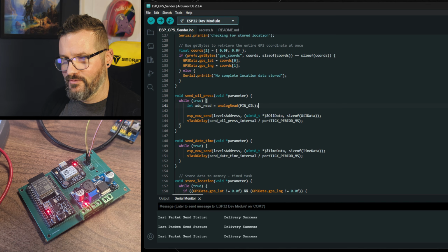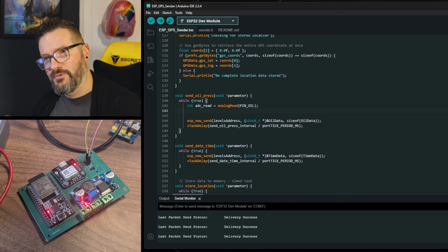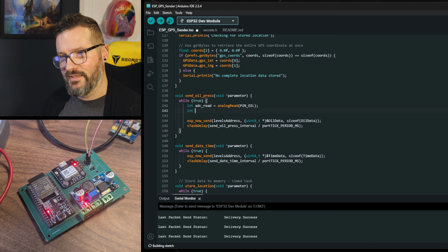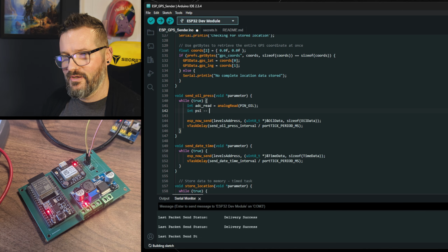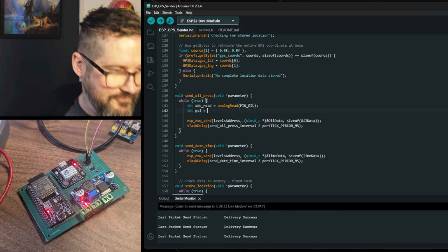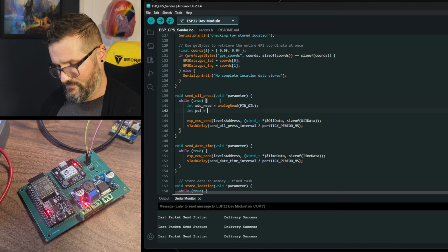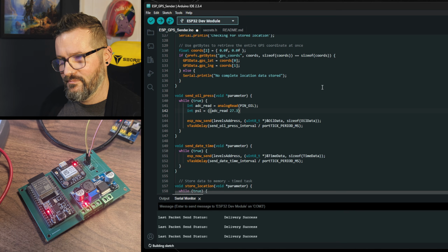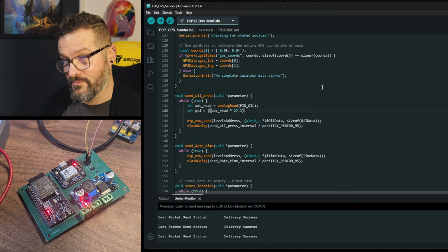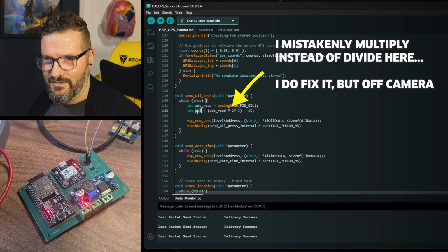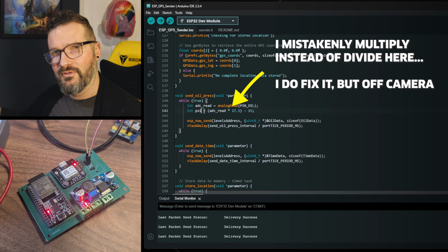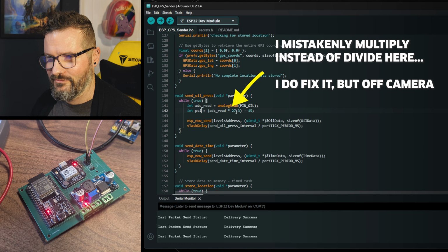So ADC read is going to be that number. Then when we've read that number, we need to put ADC read into our formula that creates the PSI. So PSI is equal to, where's our formula? So the ADC read divided by 27.3, and then it already does an int, so it'll remove any of the float after values.